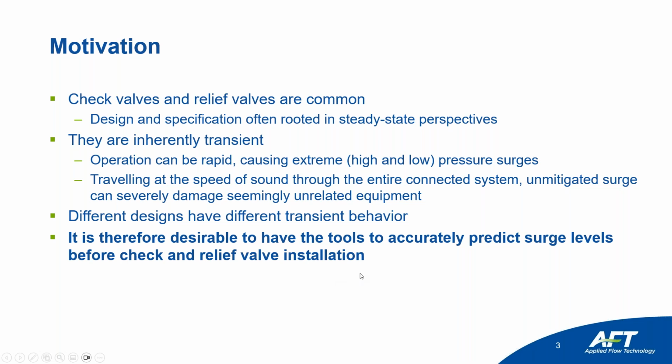So the motivation for this investigation that we did was, first, as I mentioned, check valves and relief valves are both common. You'll find them in just about any system, but the design and specification of those is often rooted in steady state perspectives. So people will size them for minimizing loss, things like that. But really, these are transient devices. If they weren't transient, they wouldn't do anything. And often, by design, their operation can be extremely rapid.